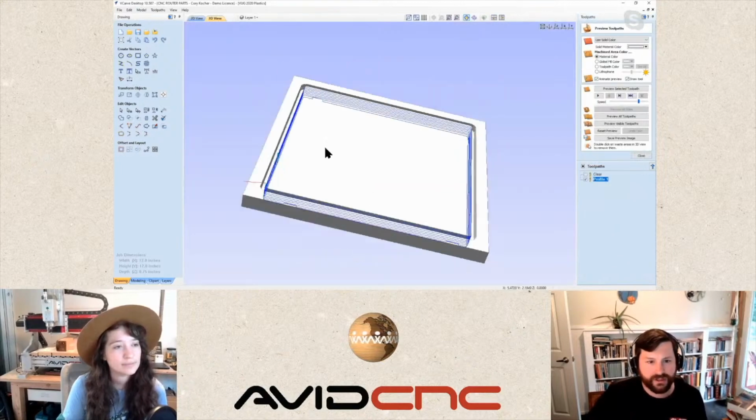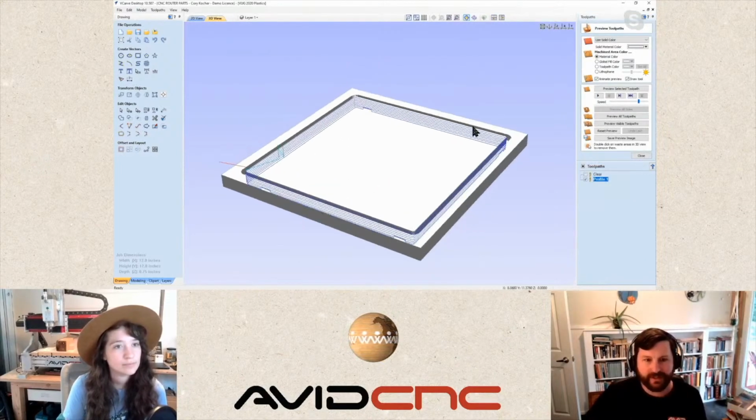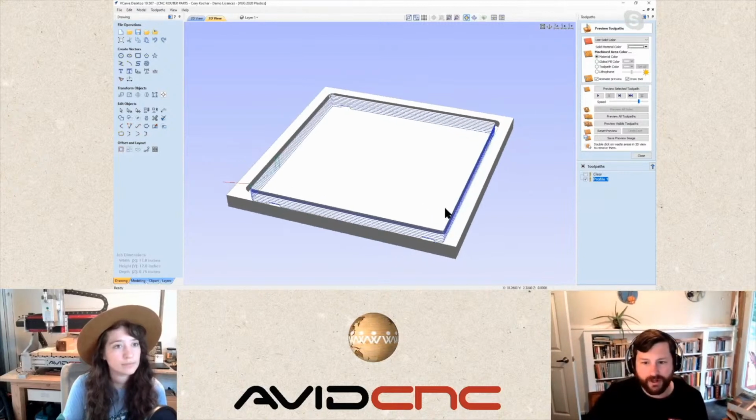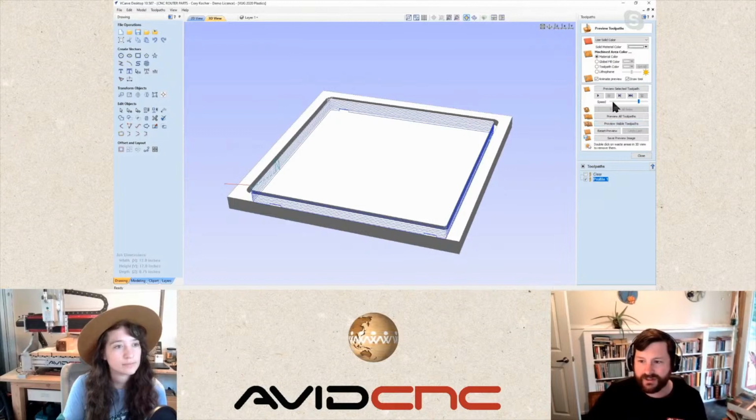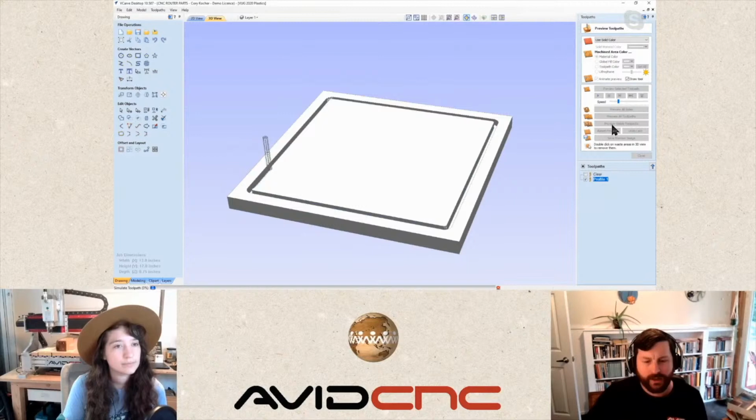And so here, I'll slow the preview speed down a little bit so we can see this. But once we get down to the bottom of our clearance pocket, you'll see that there's going to be some additional room now for those chips to get up and out of that deep canyon. And that's because we've created that additional tool radius outside of the canyon.